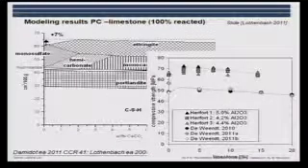And here you have the data for the impact of limestone, here the limestone percentage, on the compressive strength. And you see that this increase in volume of the solids is actually reflected in the strength of the material.